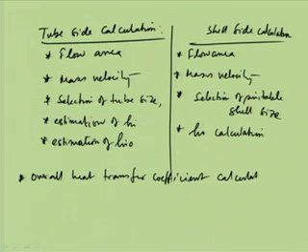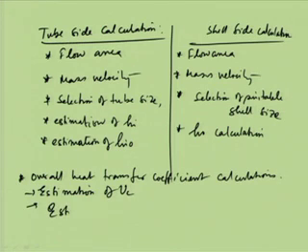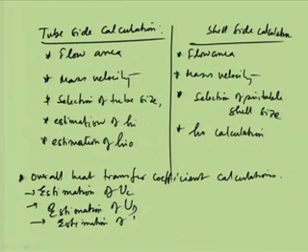These calculations indicate estimation of the clean heat transfer coefficient, estimation of the dirt heat transfer coefficient, then estimation of RD, that is the dirt factor. So, we have to check that the RD value lies in the allowable range or not.